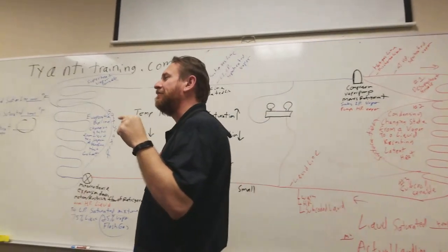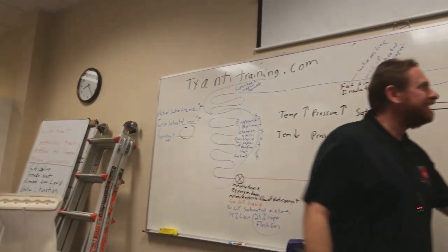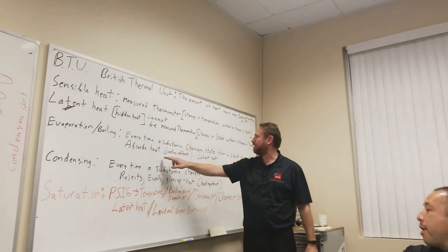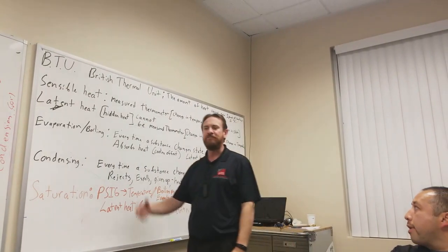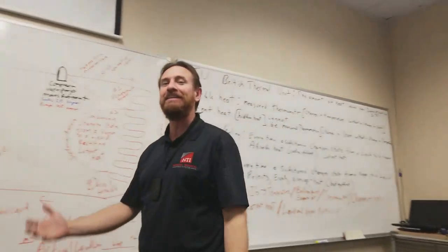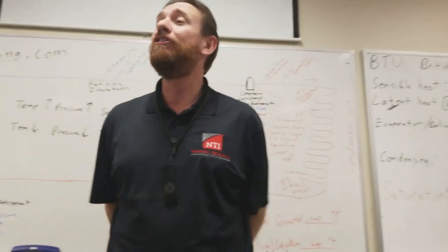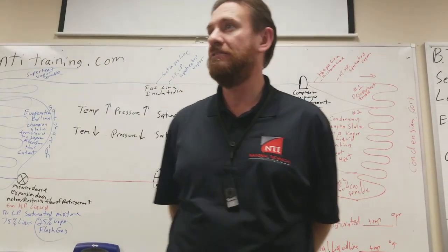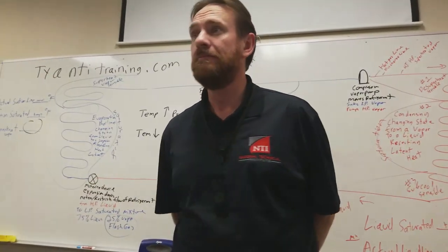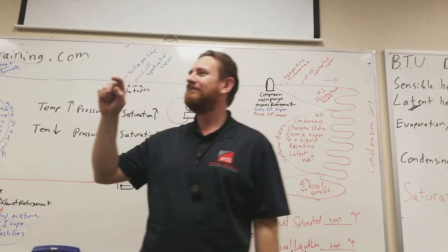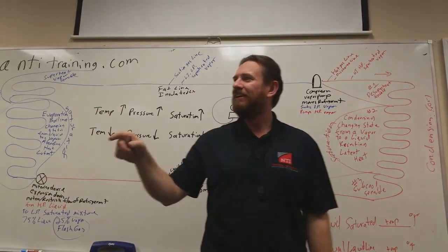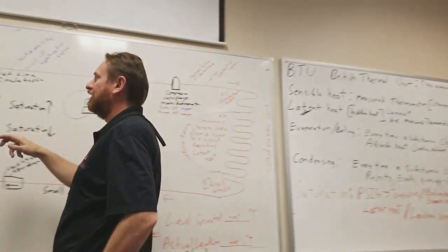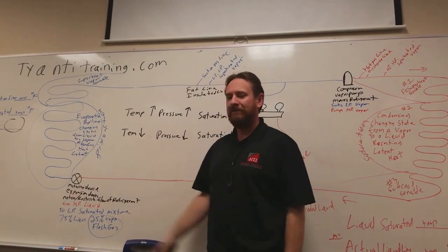But every time any substance changes state from a liquid to a vapor, it absorbs heat, which is a cooling effect. So what's happening to that refrigerant, that propane that is changing state? It's a cooling effect. It's absorbing heat. What's happening to the temperature of the remaining propane? It gets cooler. The temperature drops. All right, so the temperature of that tank dropped.